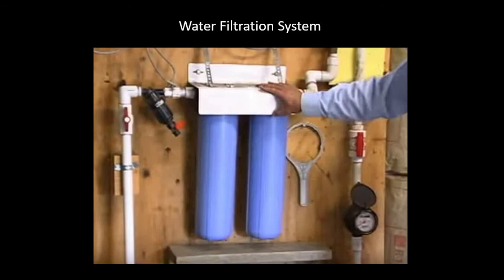So what he's got here is the first blue tube. It has a filter in it, and it's a particulate filter. And particulates are like dust and dirt and little stuff like that. And so you could even have 3 of these where they would get smaller. Like you could have a coarser filter in the first one and a finer one in the second one. Either way, the last one that he's got his hand on, or the third one in the case of a 3-part one, would be a carbon filter, charcoal filter. So that one really will clean it up. So you're progressively getting it finer and finer